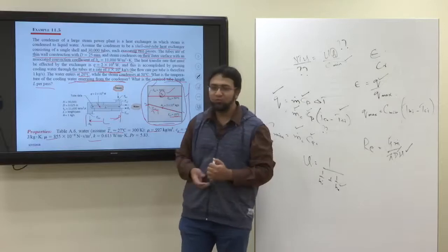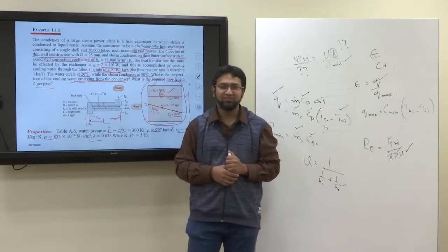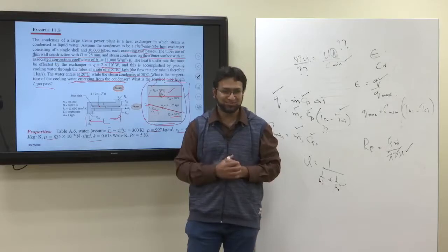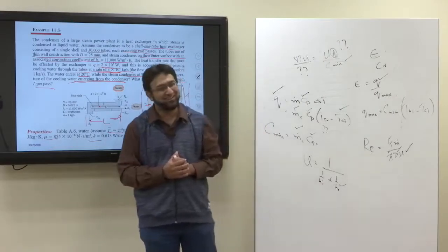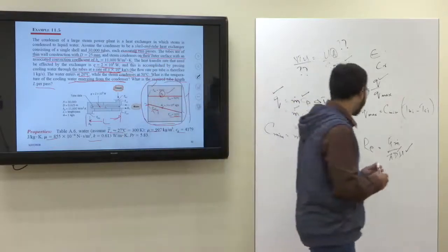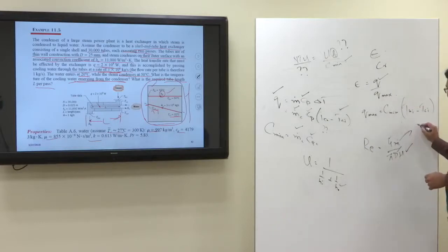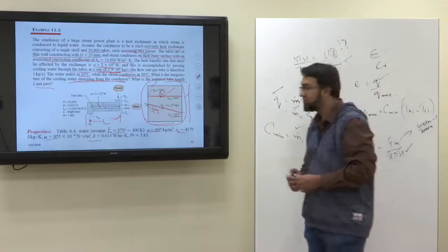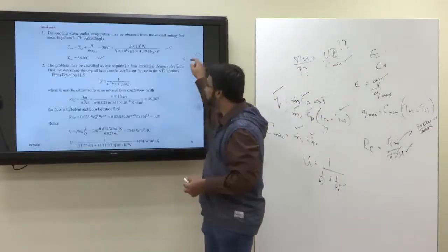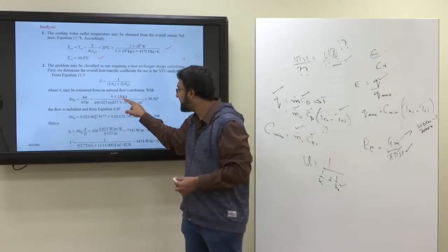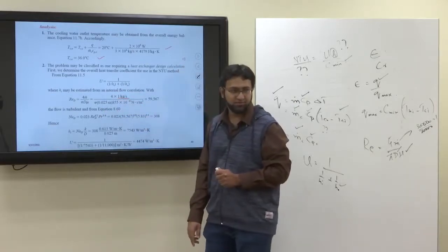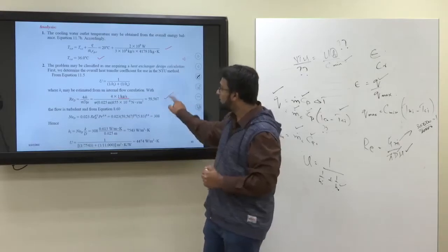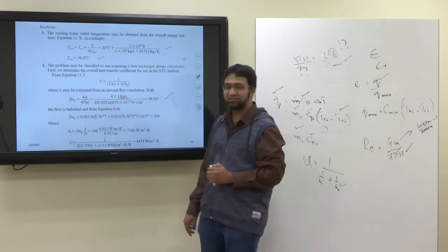So the mass flow rate here is 30,000 divided by 30,000, which will be 1 kg per second. So now we determine the mass flow rate in 4 m dot upon pi d mu. That's how 1 comes here. 1 kg per second. And the Reynolds number comes out to be 59,567.